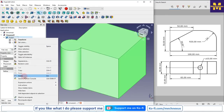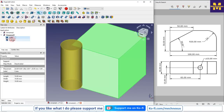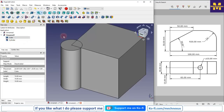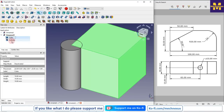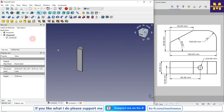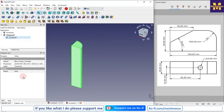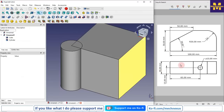Now I will delete it. Now I will select my cube and then cylinder and perform this intersection operation. You can see that everything else has been removed except the intersection. So this is how to use the Boolean operations in FreeCAD, which we are going to use in the part design here.